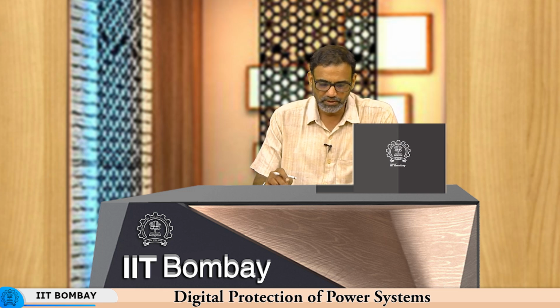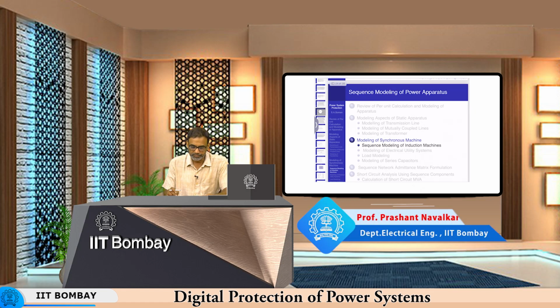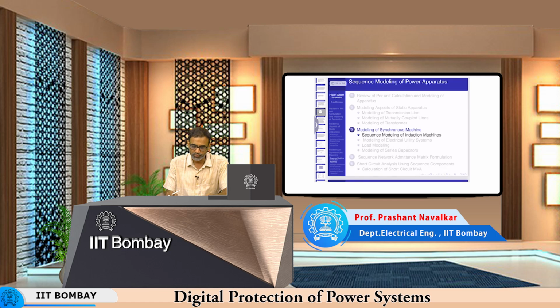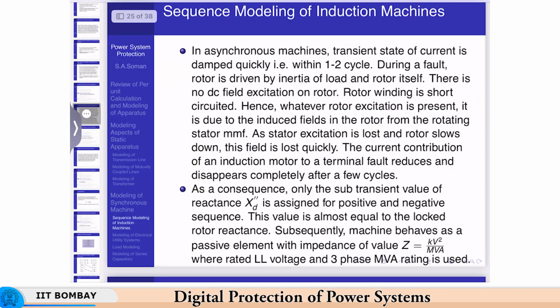So we were looking at symmetrical component representation of transformers. We had finished that and looked at symmetrical component representation of synchronous machines also. Now we will move on to sequence modeling of induction machines. So induction machines, unlike synchronous machines, are singly fed machines. That is, there is only AC excitation, no DC excitation.